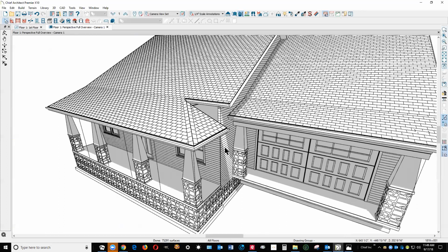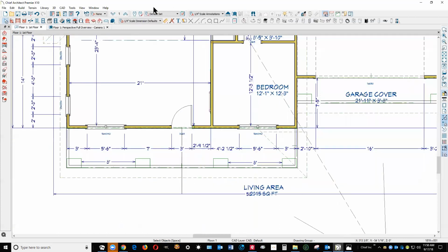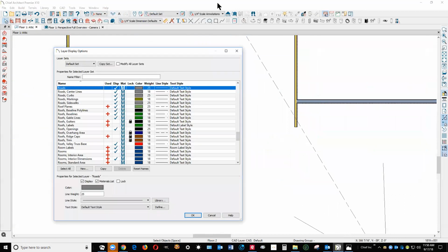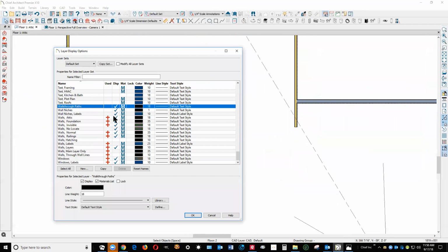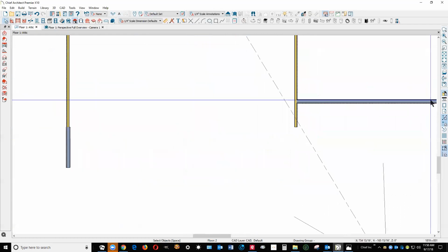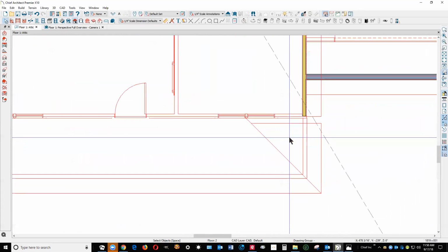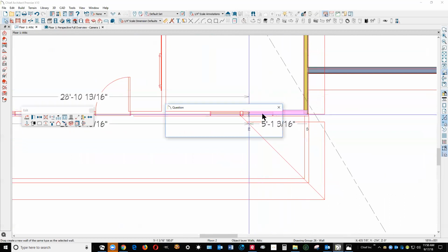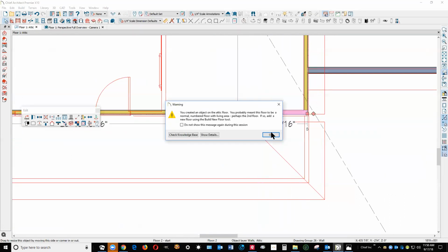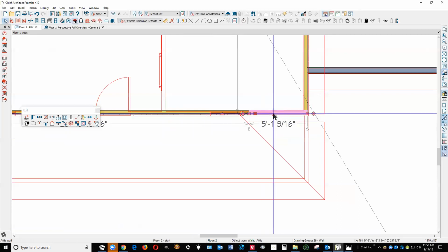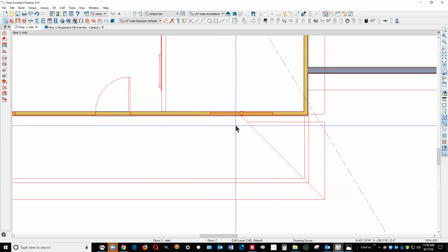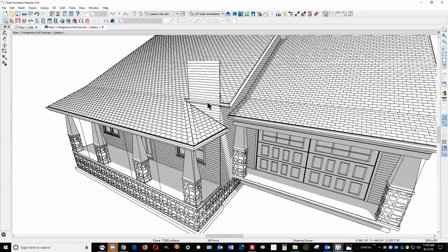Okay, now this wall's missing. Go up to the attic or the second floor and make sure that attic walls is turned on. Walls, attic, yeah, they're on. We'll turn on the reference display so I can see the missing wall, which is right here. And click on this wall and extend it. I'm just ignoring those error messages because it's just mechanical blah blah. I don't care what it says. Okay, there's that wall there.